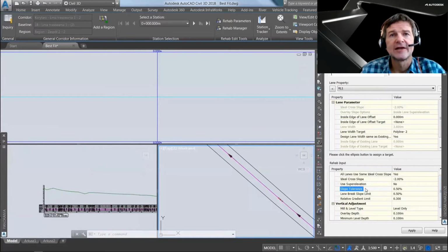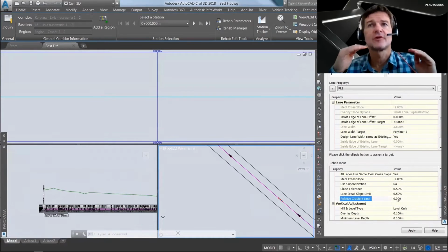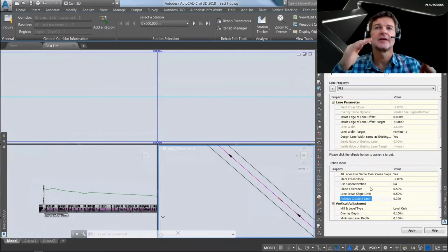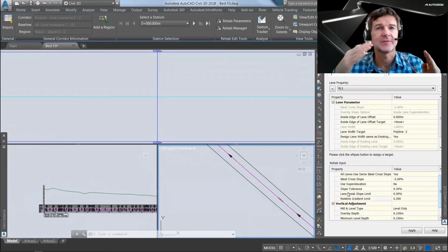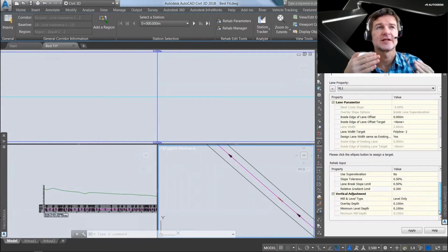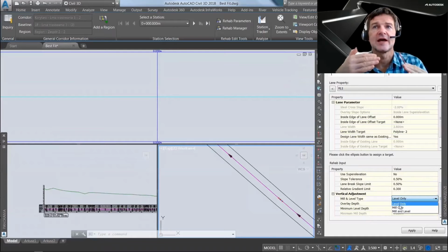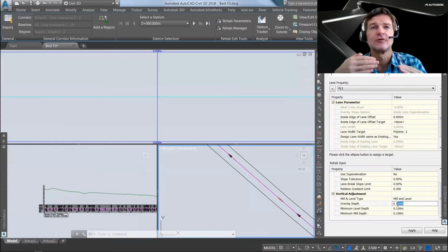And then I'm defining other properties, so I can specify tolerances, because, if you are looking for surfacing, you can say that, okay, my crossfall can change plus minus 0.5% or something like this, because of course it has the benefit because at the end you will spend less material, so it will be more economical way of doing.